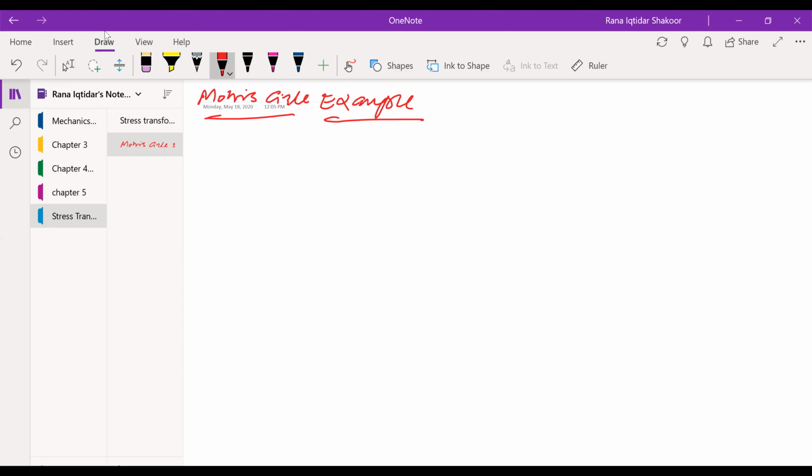Okay, fine. So till now what we have seen is that we might have some sort of combined loading conditions, and combined loading conditions may be like you may have to go for sigma x, likewise sigma y, depending upon the orientation. You might have to go for plus minus N over A, normal force over the area, that is the normal stress, chapter 2, and then you might have to go for Mc over I, that is again plus minus depending upon the direction. This is basically the bending normal stress, right?